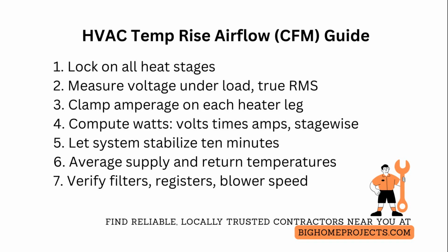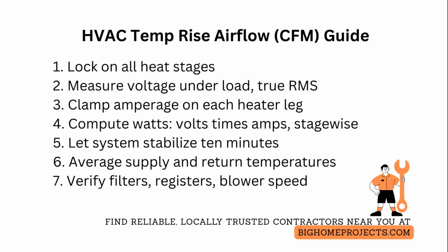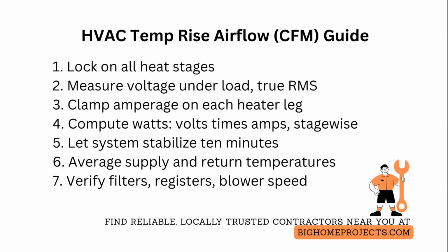Compute total electric heat wattage using W equals V times A, stage by stage, and subtract any non-heating loads on the same circuit so you do not inflate the wattage.